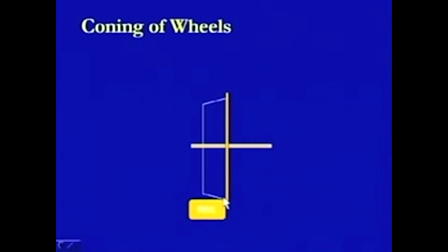What we can find here is that there is a concentration or localization of the stresses at a certain point on the rail head. When this concentration of the stresses happens, there will be more wear and tear at this location where this type of contact takes place. At the same time, because this contact is not uniform at this position, an eccentricity gets created in the rail head. If this eccentricity is created, it will create a problem for the rail sections, because there will be some bending which will get created because of the eccentricity.